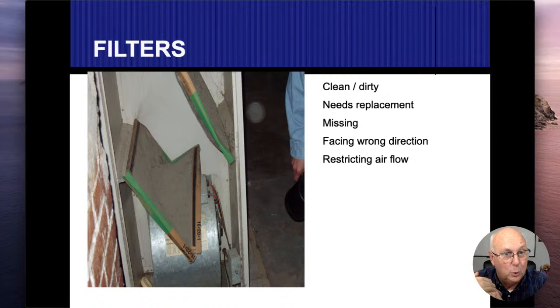Now that air conditioning coil, when it's running, creates a lot of humidity because the air inside is humid. That coil is cold. Condensation is going to form on it. If I'm blowing that dirt over that wet area, that's just going to create a cake of mud. And because there's no way to get in there without dismantling everything, if that creates a cake of mud, then that's just going to stop my airflow. And now the only cure is to either take it apart and clean it, or remove everything and put a new air conditioning coil in there. Either way, it's not going to be cheap.